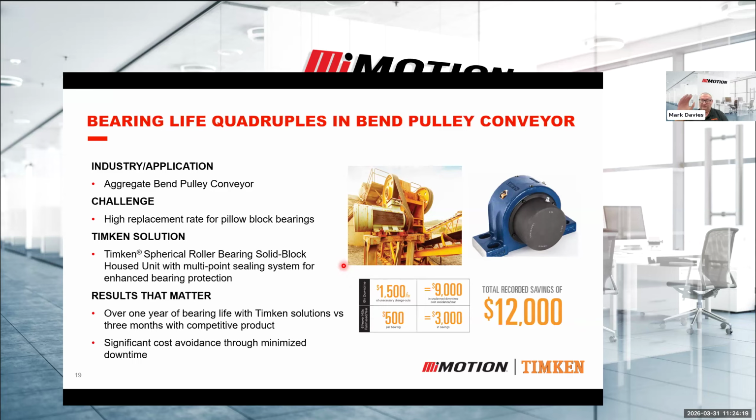But again, in this solution here, because it's a solid block housing, it's pretty much a sealed spherical inside. It's got two seals that are basically adjacent to the bearing, and it has very little volume inside for grease. So the re-greasing need is much lower because we keep the lubricant as clean as possible. You can see there the recorded savings of $12,000 over a 12-month period. So it's a very effective way of doing that, and multiple applications across site can have the same solution added to them.